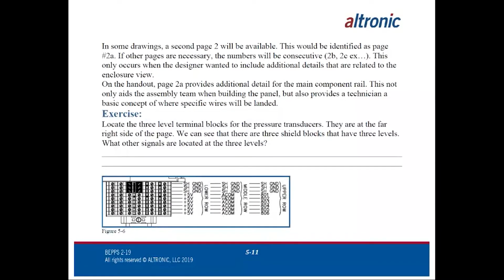They're commonly called ACOM, but they all revert back on a DE3000 system to a particular terminal on the primary terminal board with a ground symbol. So it is a ground. It is connected to battery voltage ground ultimately, but because it is through the DE3000, we'll always single it out and call it something slightly different. So it's ACOM. So it is a ground.